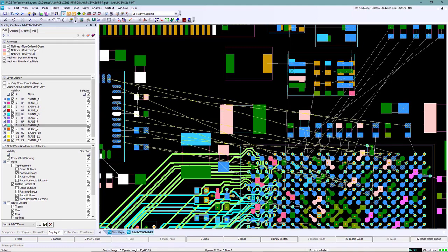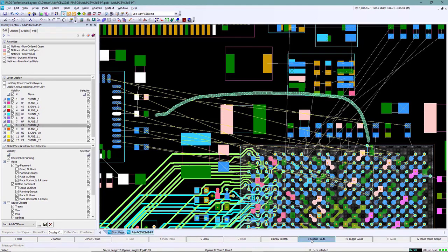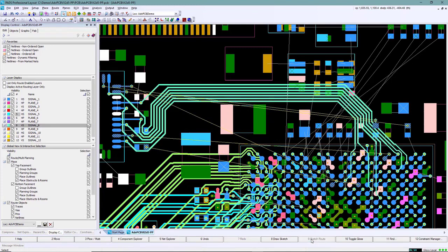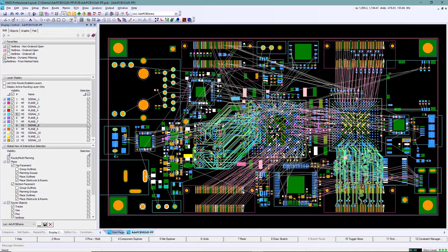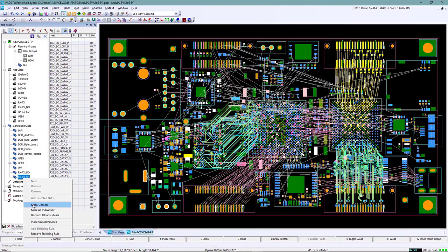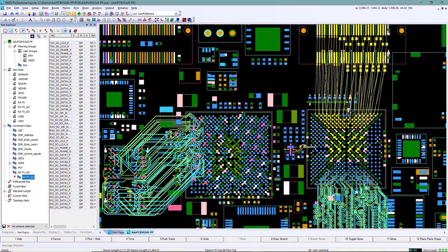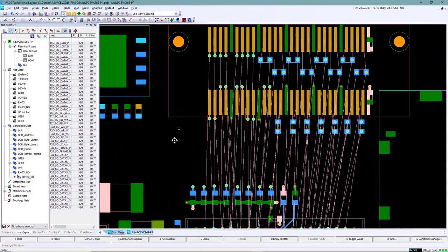Using sketch routing, we can quickly route sections of the design and even experiment with different part placements or design rule options. Another helpful netline filtering option is marking nets. Using Layout Net Explorer, all the net and constraint classes from CES can be seen along with any of those you create. Let's mark the RxTX SO class as we'll be routing these next.